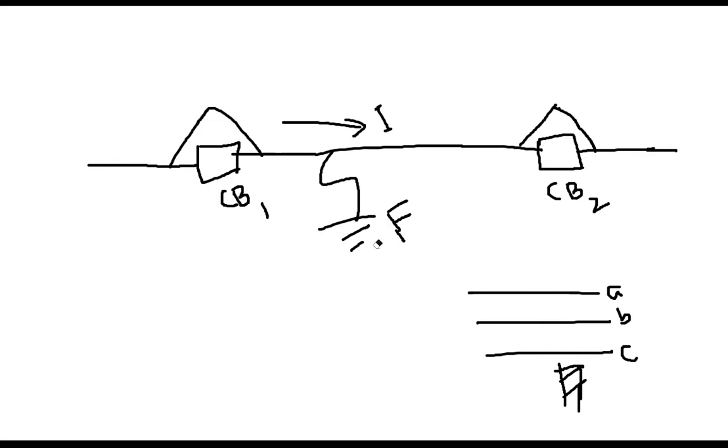Now, the example of permanent fault is not that bird or the engineer. For example, there has been a storm, and because of that storm, for example, a three-phase line, and there was a tree, and the tree is touching all three phases, short-circuited, and this is the root of the tree, and the other end is also making contact like that. So this is the best example of that 3LG fault, and it is a permanent fault. Why is it a permanent fault?